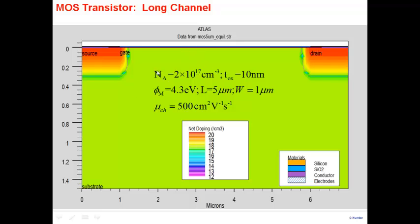You can hardly see it on this particular scale because the substrate, for the purpose of simulation, has been kept as 1.5 micron. You know that the substrates are 300 or 400 micron thick, right? So even on this scale, you can hardly see the oxide because it's only 10 nanometer here. The work function of the gate here is 4.3 eV.